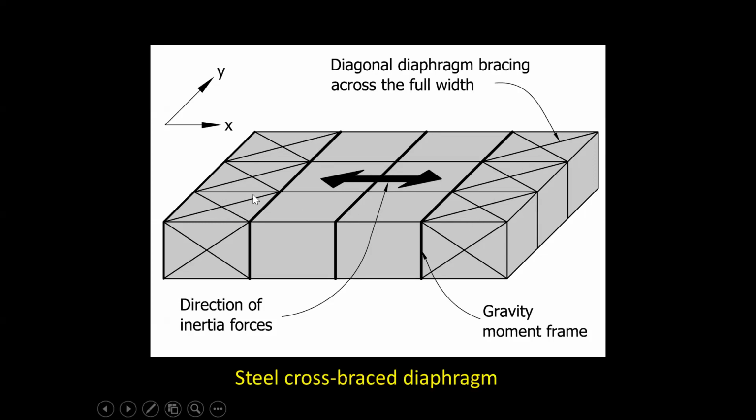And the jobs of those trusses are to transfer the inertia forces in the roof, due to the weight of the roof, the structure and the cladding. And say you might have a green roof, for example. Then the role of these trusses is to transfer the horizontal forces to this bracing on this side of the building and to bracing on the other side of the building.